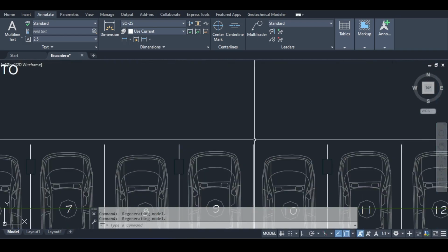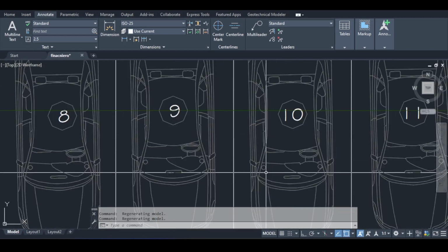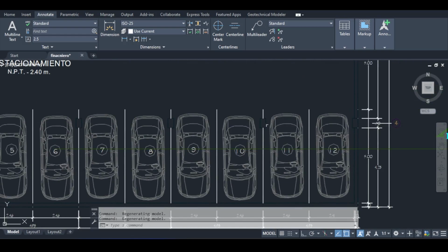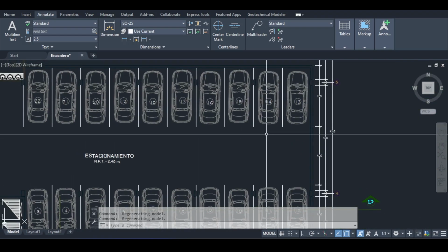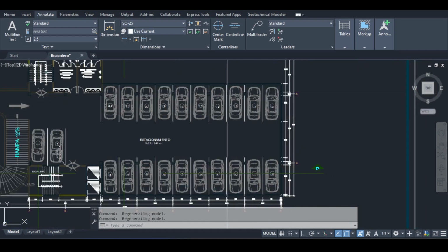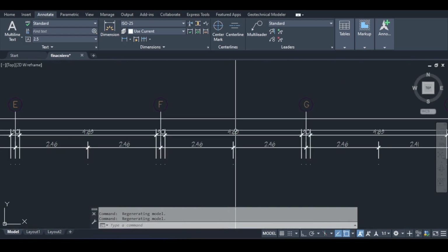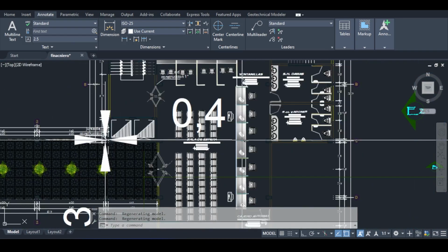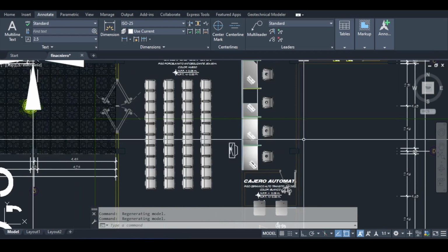Now it obviously seems that the columns were planted here, and the distance here is 4.9 meters, and the distance between this and this. I'm just thinking loudly now how I would basically slab that, because the span is what would control the slab. So the spacing seems to be 4.60, 4.90 or something. Let me check if I can move any columns. So if I check here, no, I don't think I can move anything. Those are very well placed.